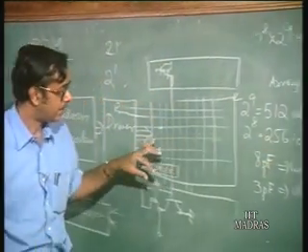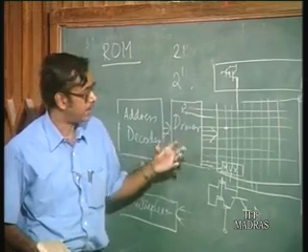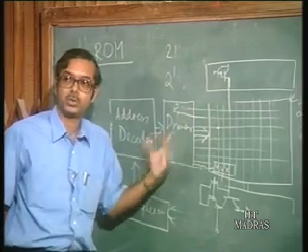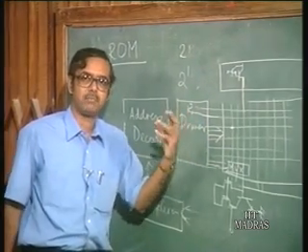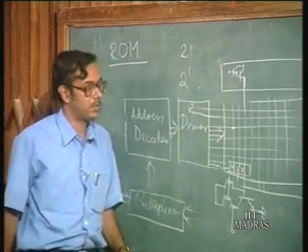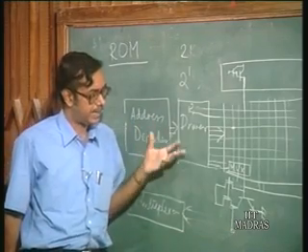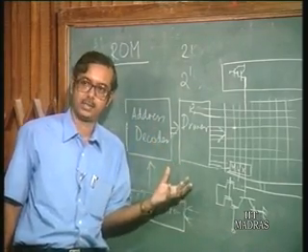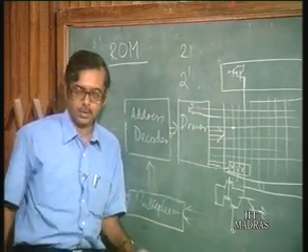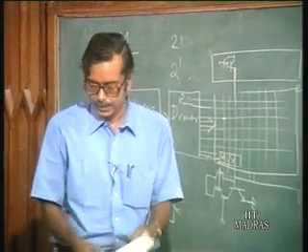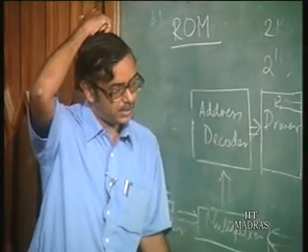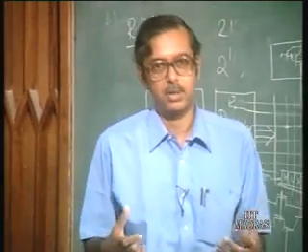Another thing is that the total number of bipolar transistors is going to be very much smaller compared to the total number of MOS transistors. You just use a few bipolar transistors, judiciously. It is not that you are using an equivalent number of bipolar transistors. So, it is not going to really affect the area by much, but at the same time you extract a lot of advantages. So, that is about this topic on BiCMOS.